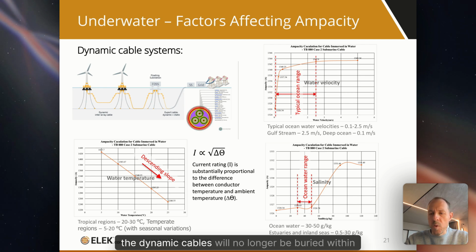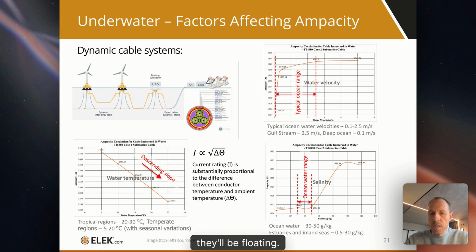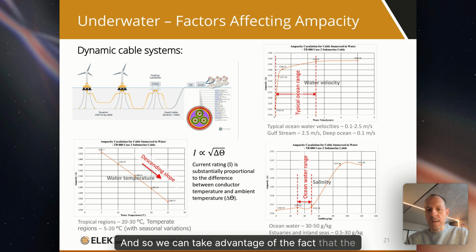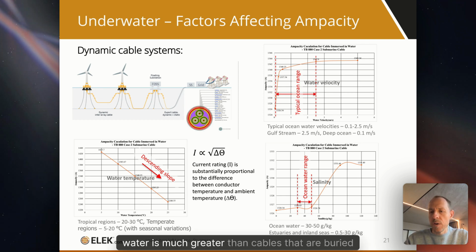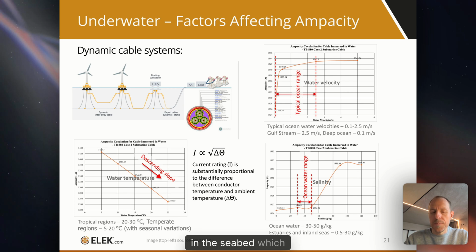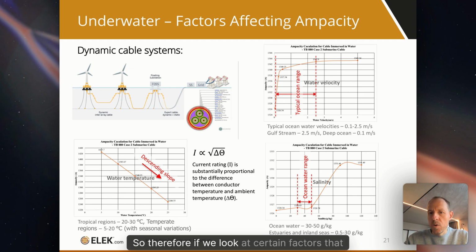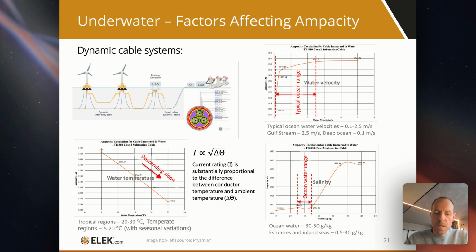The dynamic cables will no longer be buried within the seabed, they'll be floating. And so we can take advantage of the fact that the current rating of cables that are completely in water is much greater than cables that are buried in the seabed, which is a significant advantage. So therefore, if we look at certain factors that are affecting cables that are installed in water,